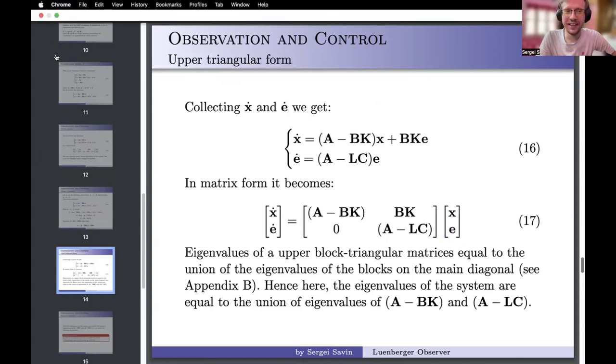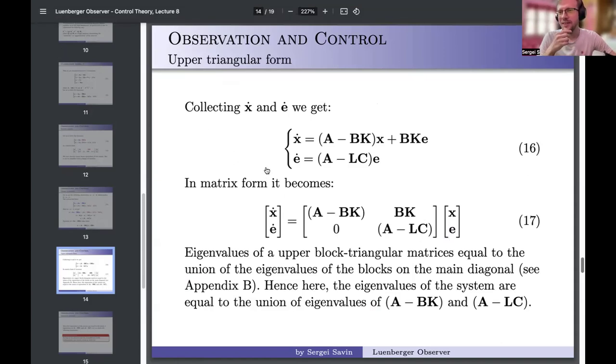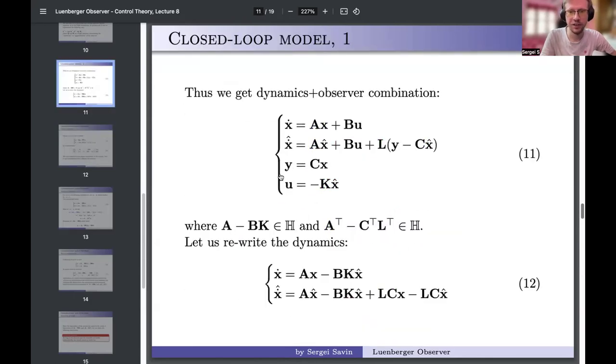And in a sense, we can talk a little bit about optimality. What you asked me before was how does optimality work here? What I can say is this. If our optimality can be expressed in terms of the eigenvalues that we obtain, so for example, we get our optimal LQR controller, which gives us the controller gain K, optimal in terms of the cost function, right? And we get the performance of the system expressed in terms of the eigenvalues of the system. All those eigenvalues are preserved here. So even as we use our controller not as minus Kx, but as minus K x hat, right? This is our controller. Remember, this is our controller.